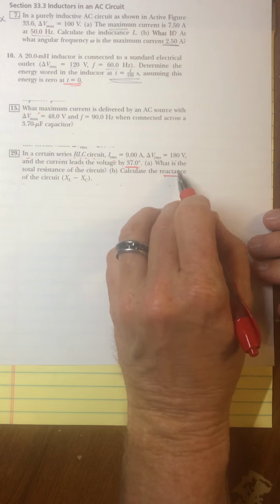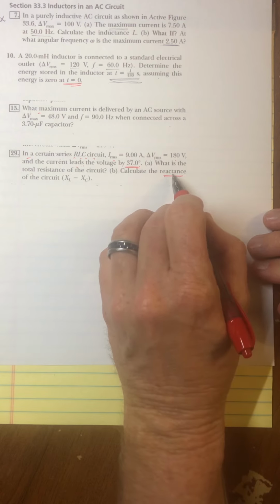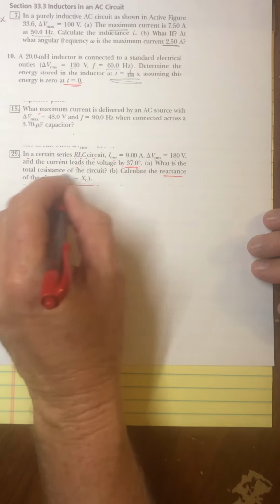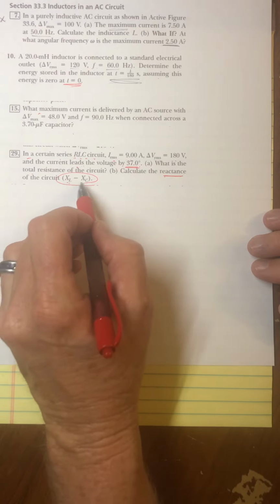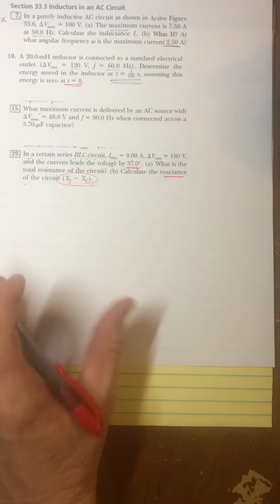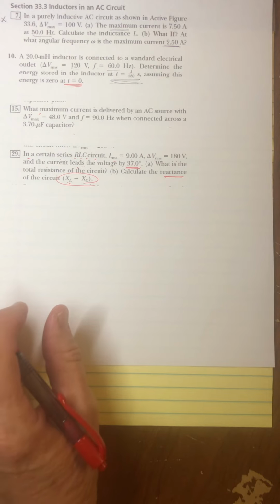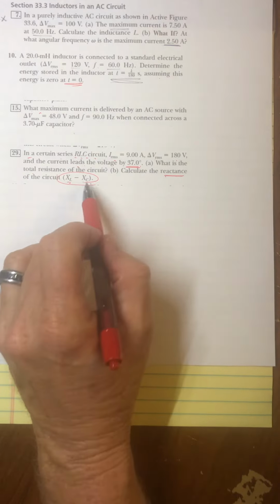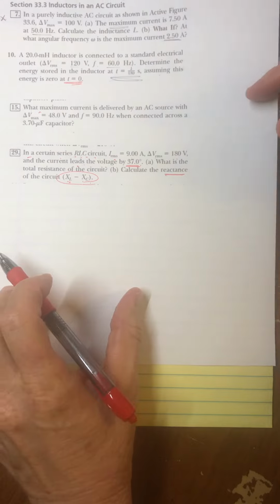They don't say reactance of the inductor. They don't mean the reactance of the capacitor. They say the reactance. And so the combination of the L and the C together. So we're not going to be able to find them individually, which kind of makes sense. I think we would need 3 equations to find those 3 unknowns. And it sounds like they've given us enough to get 2 equations. So we need to think of this as one unknown and the other one being the resistance.